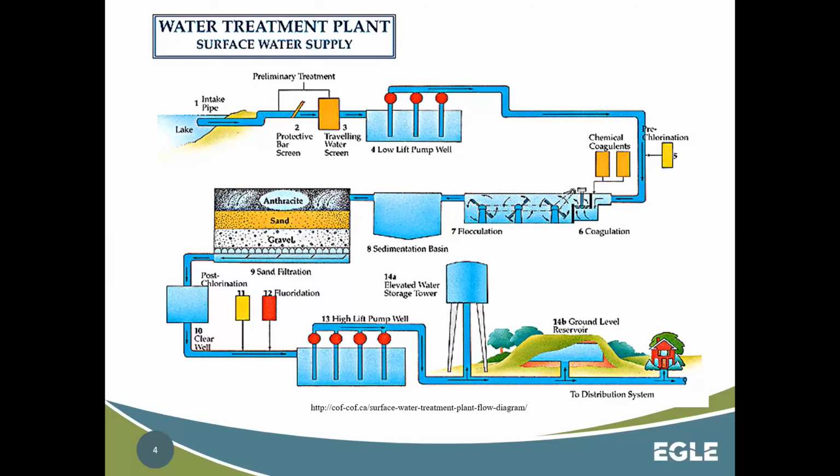Those low lifts in turn push that water to the filter, the treatment plant, usually at a higher elevation. And through there, we'll go through another pre-chlorination, and we'll go through the coagulation and the flocculation of the water, right? We'll perform that settling of the floc. Here also, we might have a lime softening settlement. But once that settlement is done, this is where those sludge pumps would come in handy to take that sludge from the settled sediment basins. The clear water goes through the sedimentation basins and then to our sand filtration.